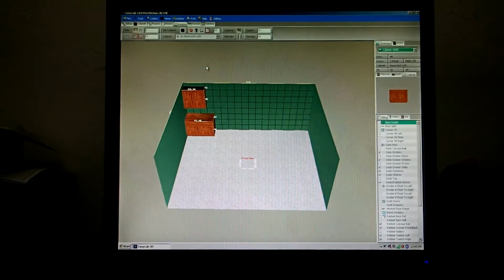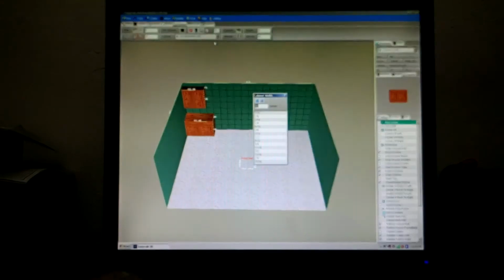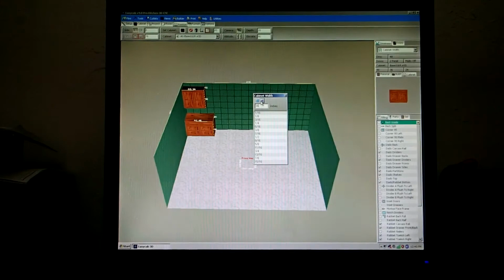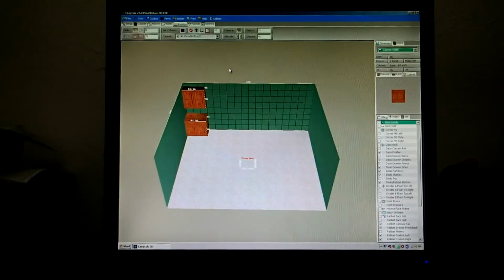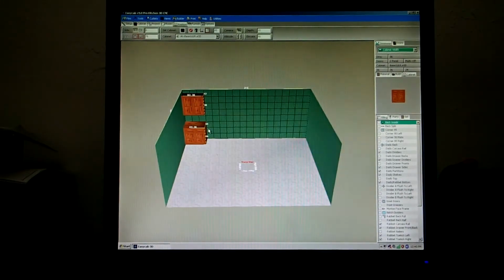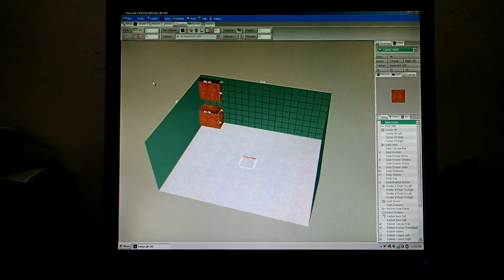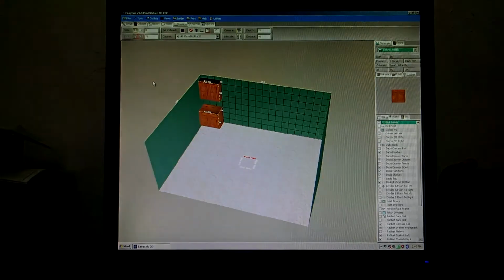When you change a cabinet's dimension that's in a room, say like A1, if we select it first and then we press enter, then we'll change that 48 to 36. When you do this, this does not change the width of the cabinet in your library. That remains the same. This just changes the cabinet in your project.